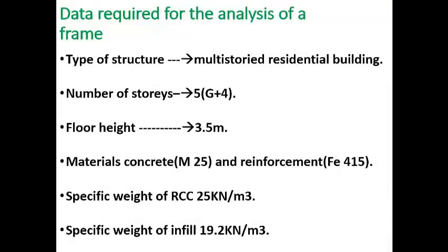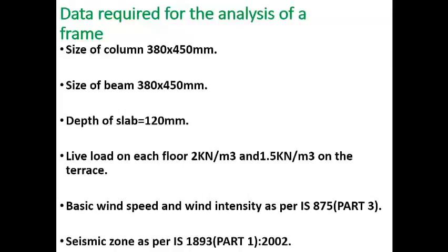Data required for the analysis of frame. The type of structure in my project is a multi-story residential building. Number of stories is 5, floor height 3.5 meters, M25 concrete and Fe415 steel. Specific weight of RCC is 25 kN per meter cube. Specific weight of infill is 19.2 kN per meter cube. Size of beam and columns are 380 by 450 mm. Depth of slab is 120 mm.